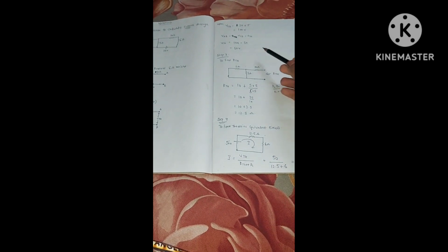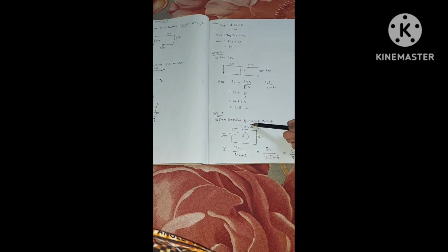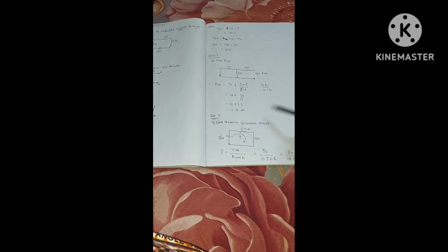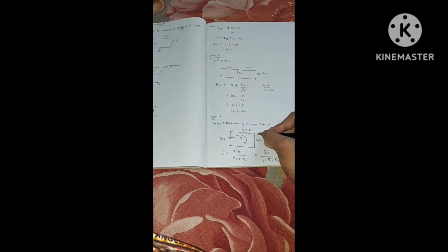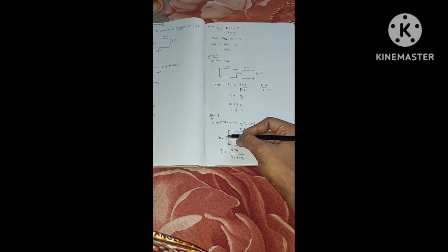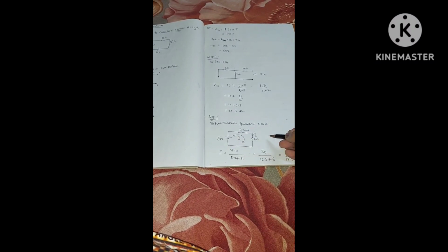Okay, so drawing this Thevenin equivalent circuit, how we found the VTH? So we wrote 50 volts here. We found the RTH, we wrote the RTH here, VTH, RTH, and finally RL. We find the current through RL, that is we find this I. I'm doing this just to explain how the current is flowing in this circuit. This is the positive terminal, the bigger line is the positive terminal, this smaller line is the negative terminal. Current flows from the positive to the negative, right?